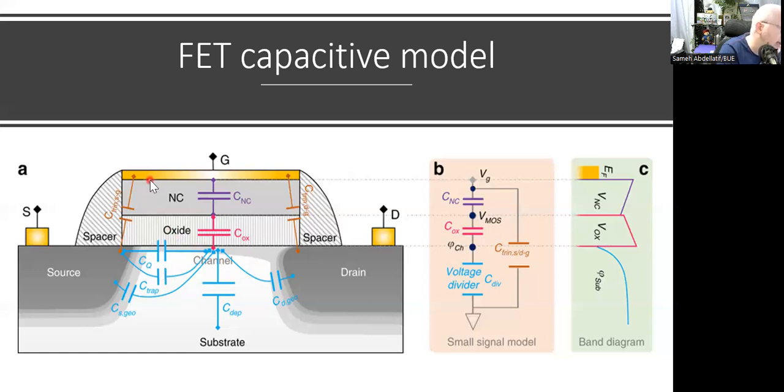Between the metal and the semiconductor, we have what's called a metal semiconductor junction with a depletion region and a capacitor. That's why we have all these different capacitance models that, as I mentioned, may influence the operation of your transistor based on the frequency of the operation and based on the condition.